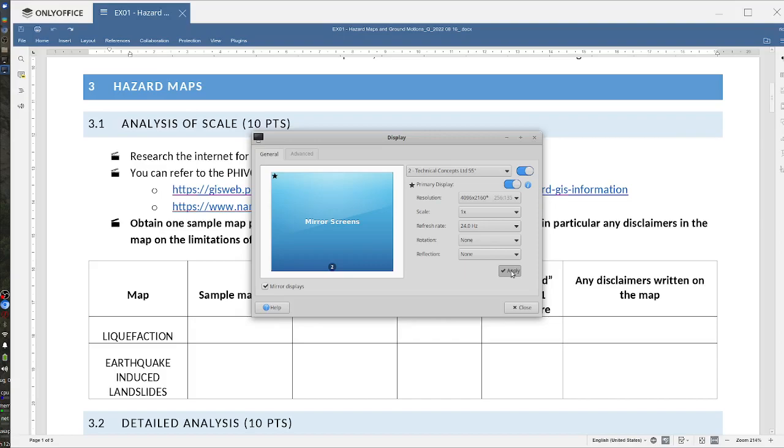And then once you have those three faults, calculate their earthquake magnitudes using the Wells-Coppersmith equation. Just assume that the length of the fault is the rupture length of the fault. Okay. So this will not be an exact science because some faults are segmented. Some faults are not necessarily straight. So just try to approximate the lengths.